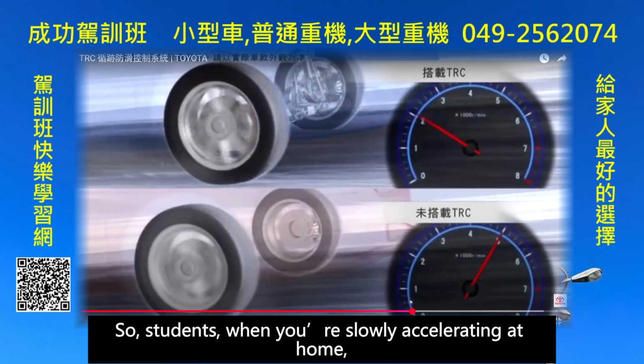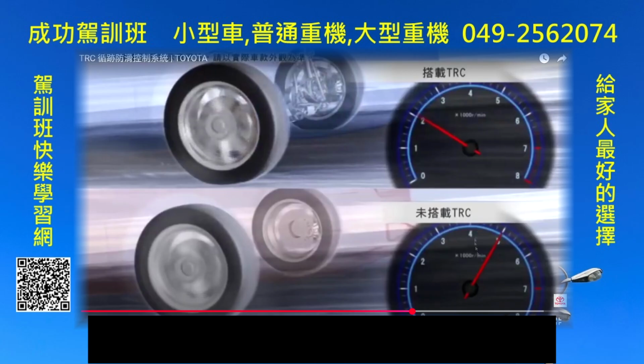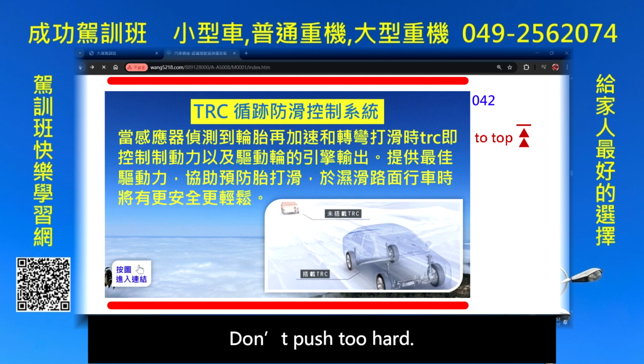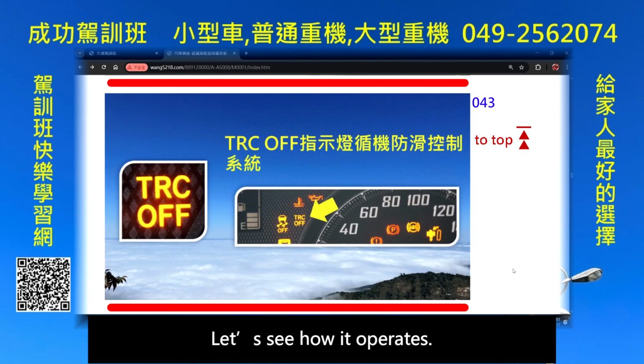So students, when you're slowly accelerating at home, pay special attention to throttle control. You need to learn to manage the gas. Press gently. Don't push too hard. If you push too hard, it easily leads to slipping and losing control. There's an indicator light here. It can be turned off. The traction control system indicator light. Let's see how it operates.